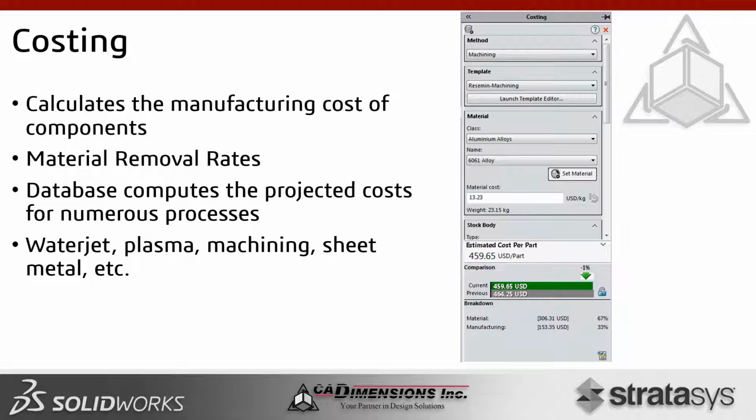If you're working with a sheet metal part, it'll calculate all the cost of the bends that you have to do. It also includes your setup time. If you're machining something that has 3 different setups on it, it knows that there's going to be 3 setups, and it will include your setup time and the setup cost that's associated with that. So it definitely is super helpful to calculate the cost of machining something to quote. You don't actually have to create the program to then quote, and then not get the job. So it does remove a lot of hassle that way.